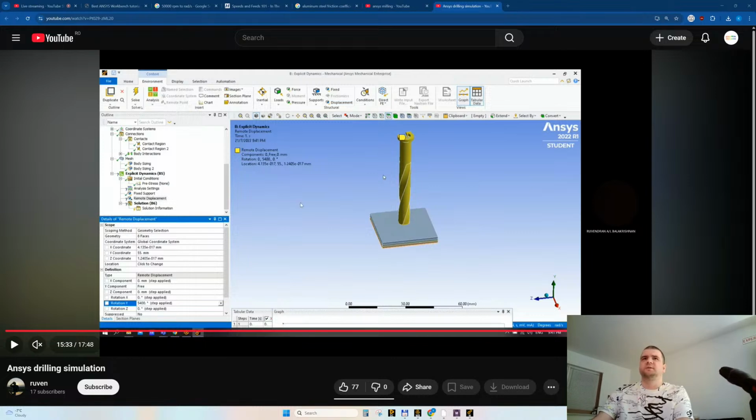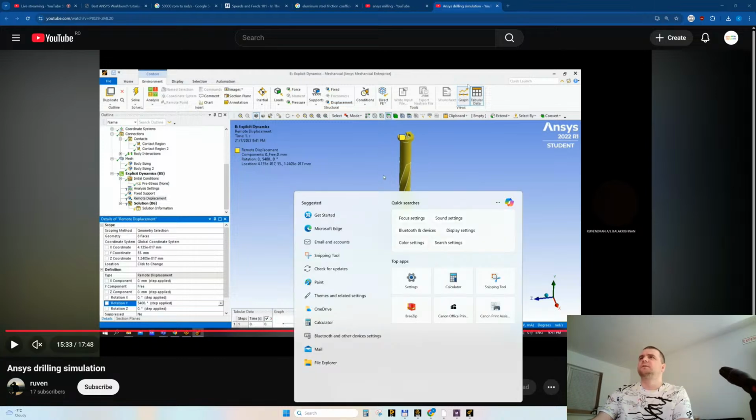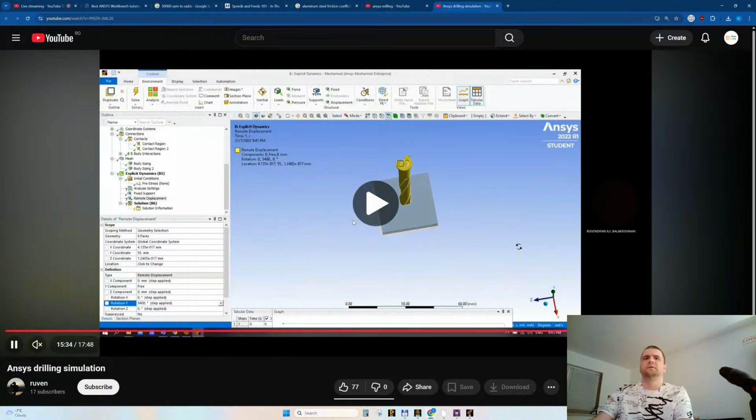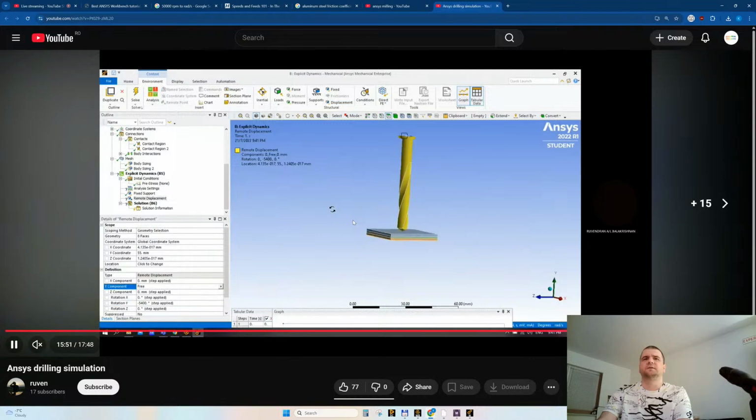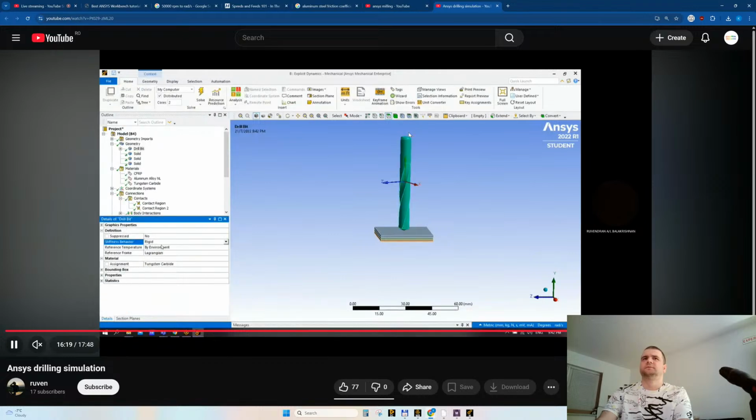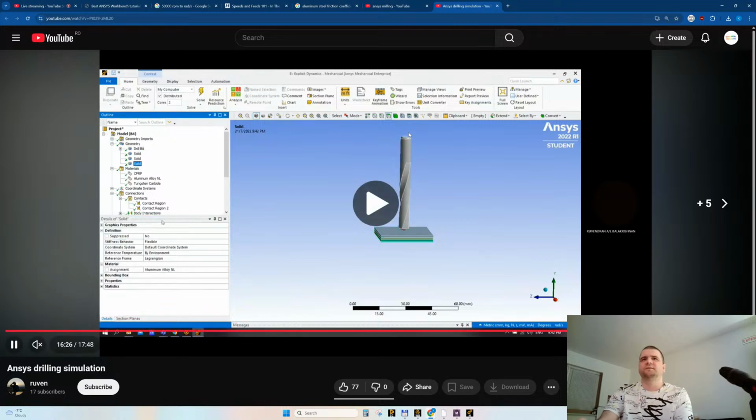All right. But remember that someone should translate, either the tool or the plates should translate. The plates will not translate because they are fixed, so he needs to also apply a rotation and an axial translation. Y8, and it's not correct because it's on the outside. He does not see this. He made the drill bit rigid. Why did you assign the tungsten if it's rigid? Rigid means infinite stiffness, so yeah.